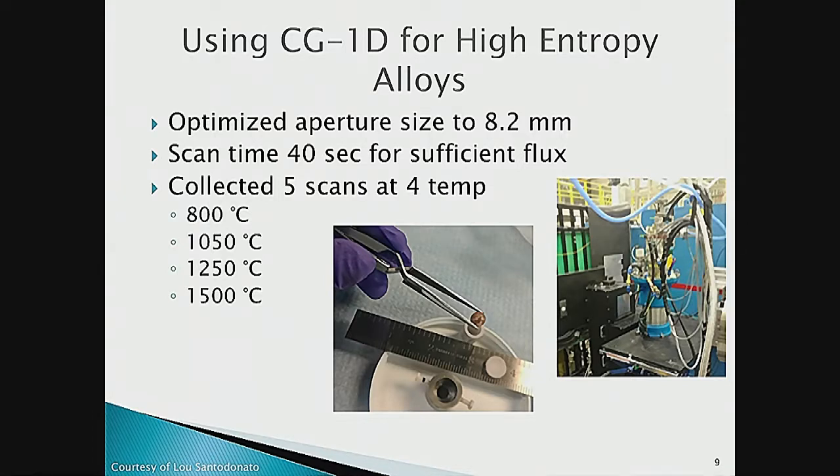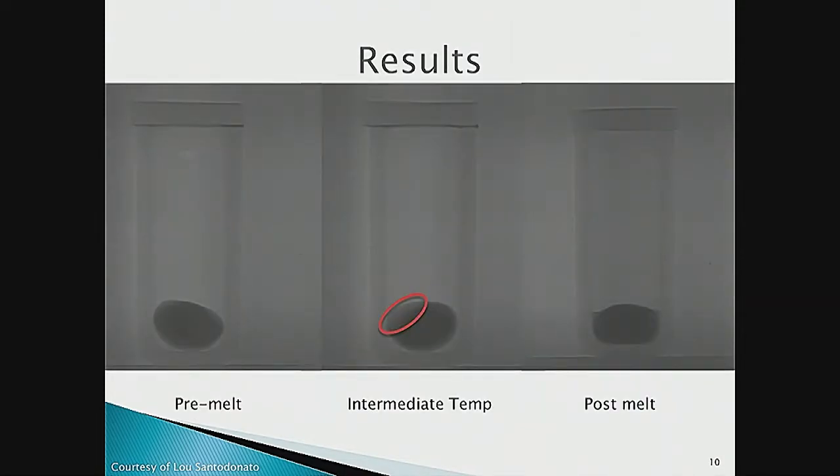With this, we then proceeded to program the computer to run scans across a range of different temperatures. So Nick, specifically, chose 2 temperatures which were less than the melting point of this copper-rich phase, a temperature that was in between the melting point of the copper-rich phase and the non-copper-rich phase, and then something that was floating around the melting point of the entire system to see what's happening as we transition up the temperature there, which Stephanie will talk about.